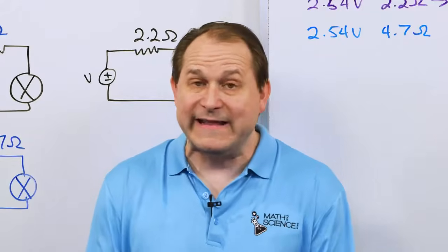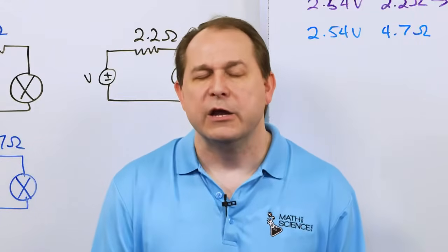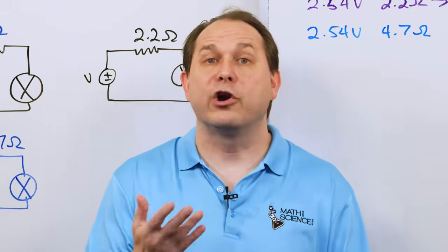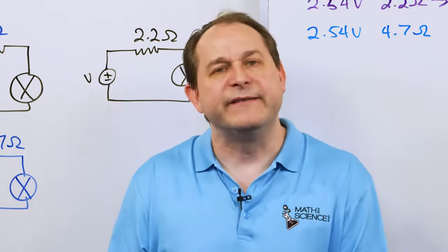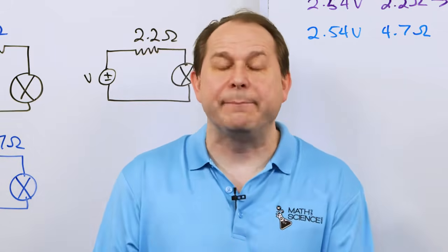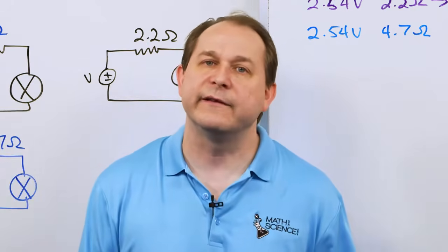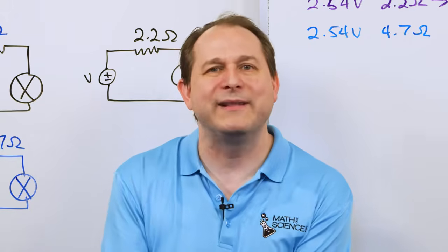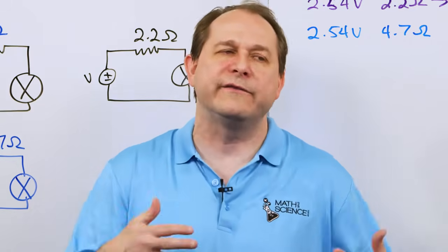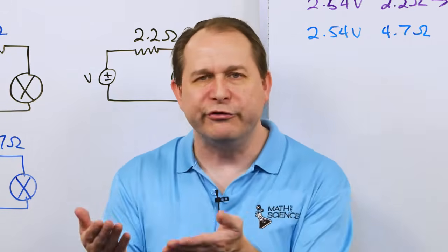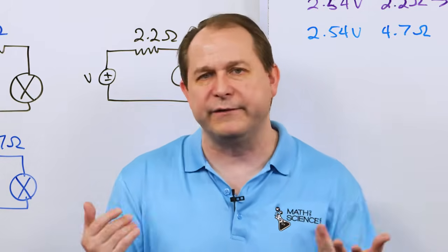So what happened in that case is I designed the circuit, so to speak, to operate at a certain amount of current, right, that this light bulb is designed to take. But when a short circuit happens elsewhere in the circuit, the current surges because you're bypassing all the resistance in the circuit. You put the resistor in place in order to make the current the right level for this light bulb. When you circumvent it, the current spikes and it burns out the light bulb.